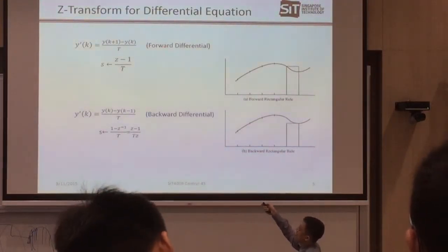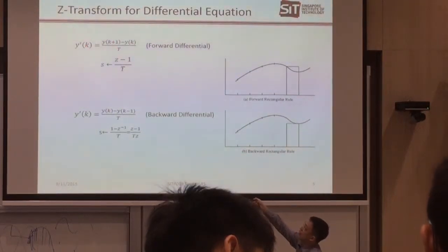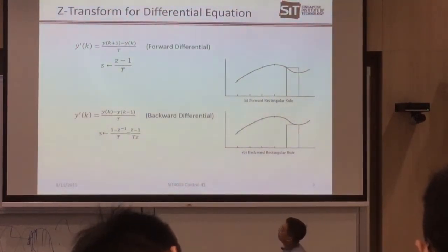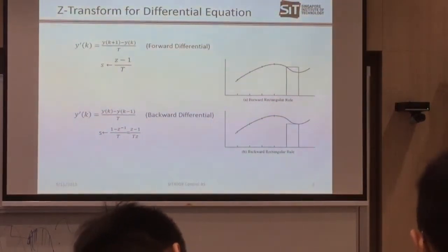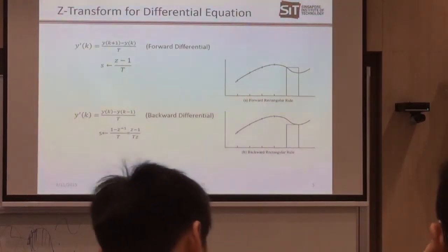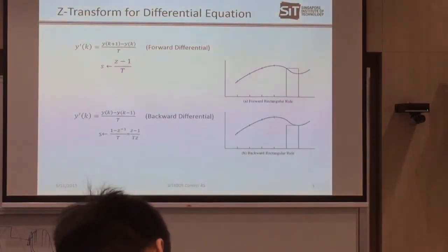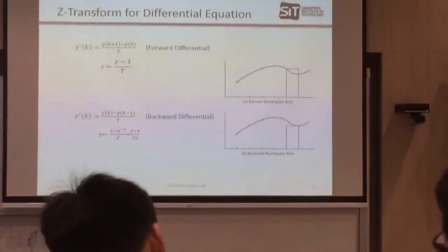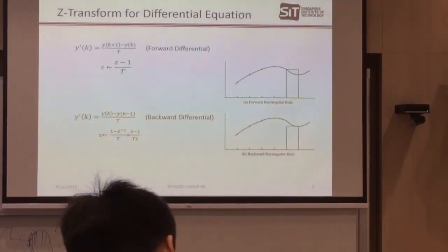If you are looking at the forward differentiation, your differentiation is your next step minus your current step, divided by T. So what we mean is, if you have the differentiation of yt, you put the Laplace transform, you will get your S multiplied with Ys.